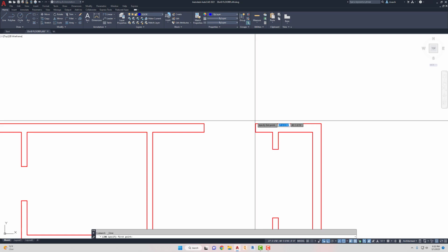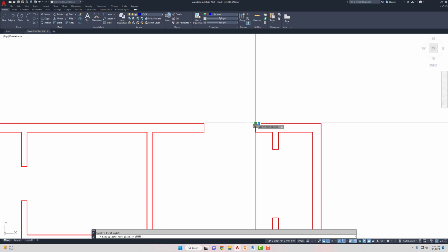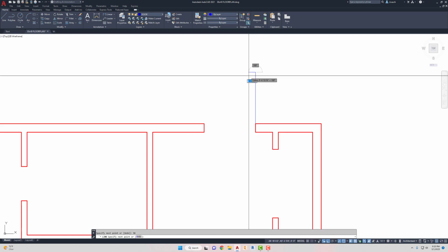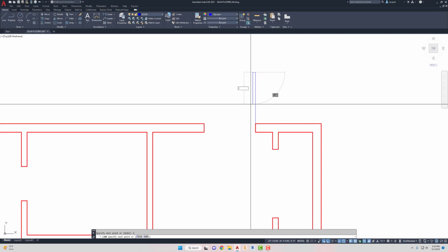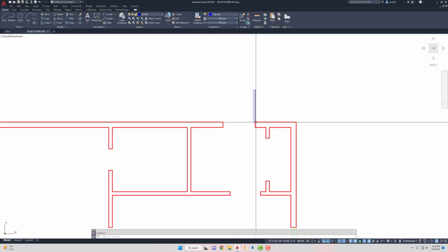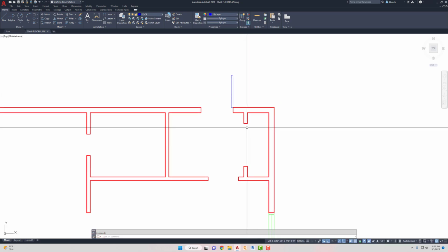This door opens up, the hinges on this side. So I'm gonna start my line on this corner and draw it straight up. This one is gonna be 36 inches tall, so 36. I'm gonna come over to the left, make this 2 inches wide, come back down 36, and then back over where we started. So that's our door fully open right there. Like I said, we'll come back and do the door swing later.